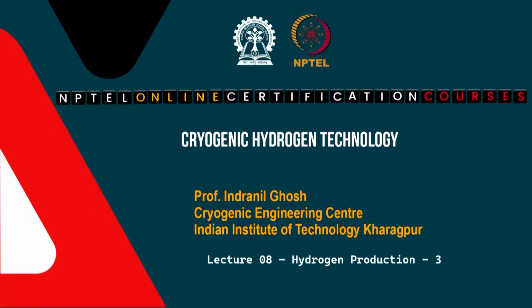Welcome to this lecture on cryogenic hydrogen technology. We were talking about the cryogenic hydrogen production, and in continuation to that, we were talking about the different conventional processes like steam reforming, partial oxidation and autothermal reforming. In that context, we have also learned that this resultant product, that is the CO and H2 combination, needs a certain amount of processing to get the H2.